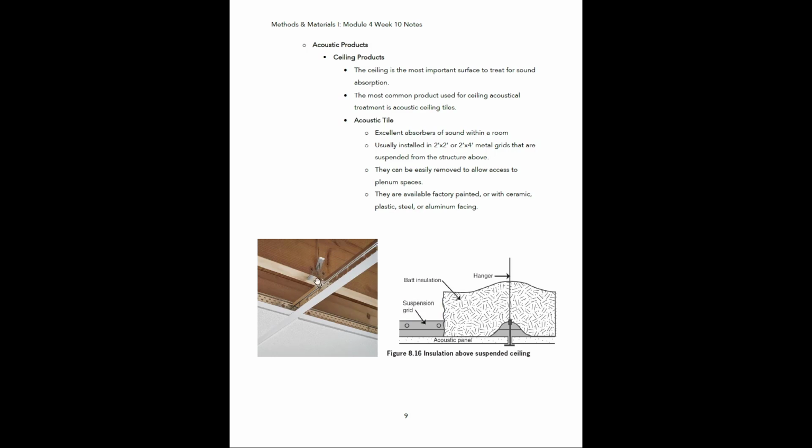All right, and the distance of this wire can be adjusted, okay? So you can see right now it's actually pretty close to the joist itself. It's not suspended down very far, maybe an inch or two, but you can adjust this and make the ceiling drop lower and lower based on whatever needs you have.